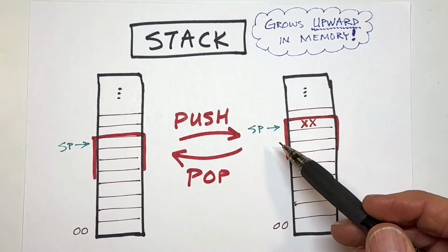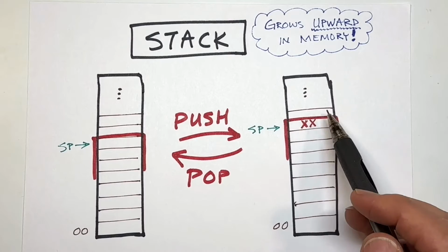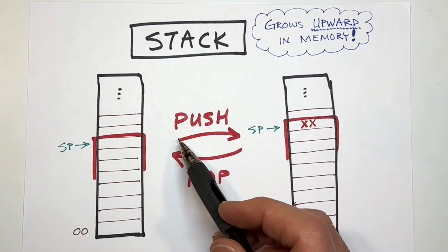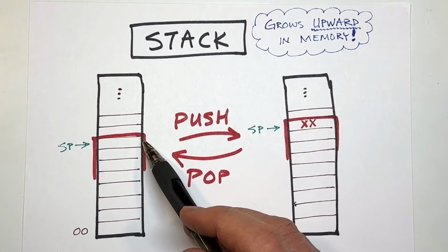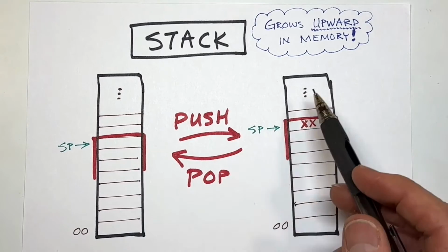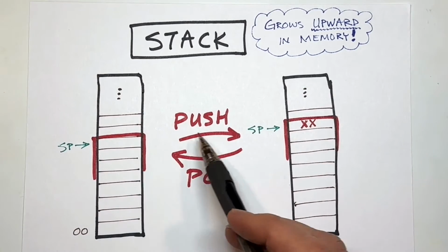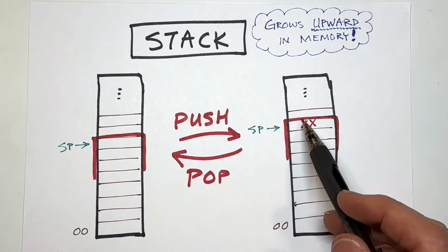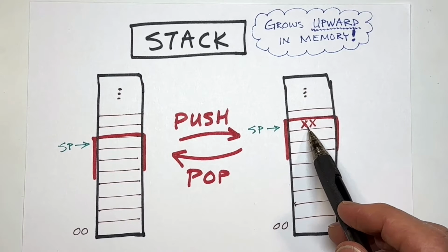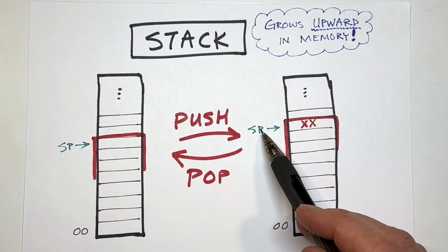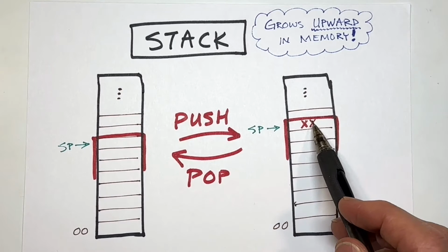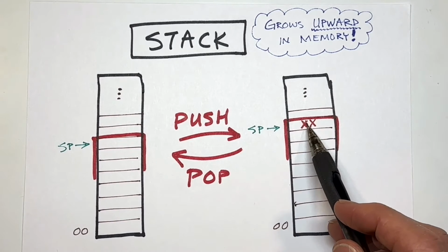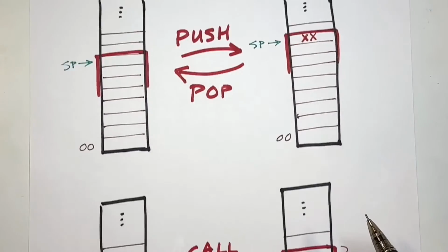And if you are programming in other operating systems, such as Linux, you might be used to the stack growing down from high memory. But here, it's growing upward. And so the push instruction will take a byte and push it onto the memory, increment the stack pointer, and then use that as the address to push or to store into, and pop goes the other direction.